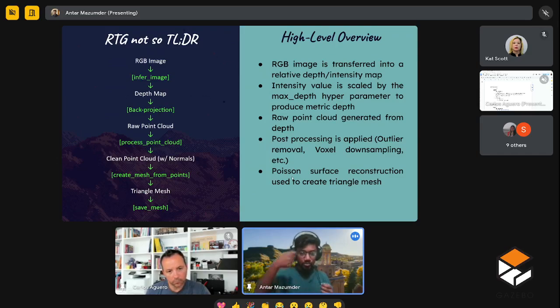And then we're going to wrap a sheet around it, using a process known as the Poisson surface reconstruction method. And that's going to give us a primary mesh. And after that, we're going to post-process it further in software called MeshLab, and wrap it in an SDF file to export into Gazebo. That's the basic idea.